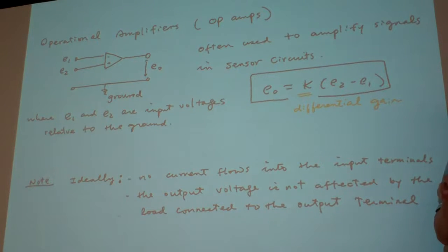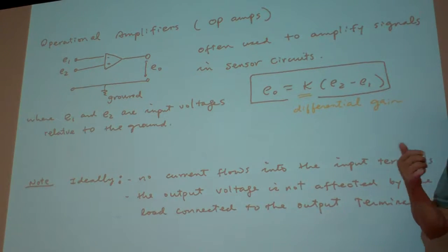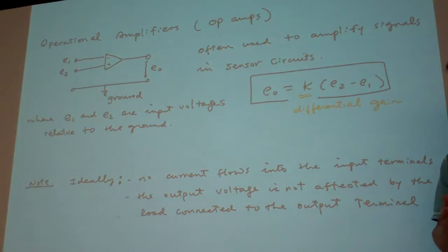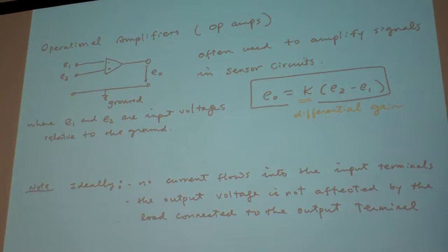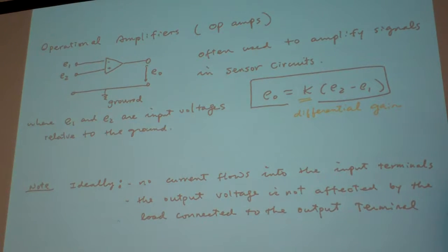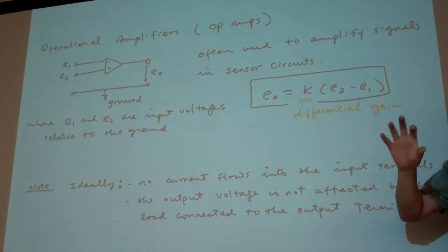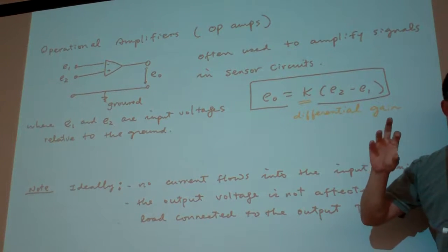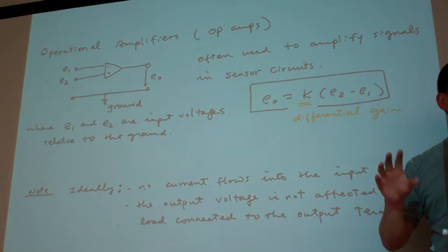I want to take the detected signal in terms of current and feed it into a computer for further action. The computer, the PC or desktop, can take voltage in either the 0 to 3 volt or 0 to 5 volt range, and the current is about milliamps.